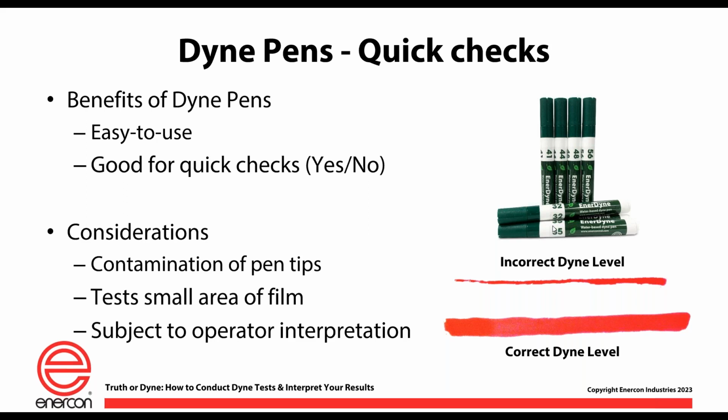So these test methods have some downsides to them, these Dyne pen test methods. First of all, a lot of the films that we treat, folks, they have additives in them, and some of those additives come to the surface. So I'm thinking specifically of slip additives.